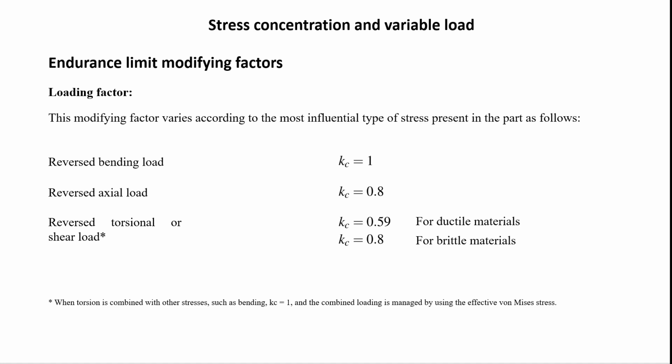Loading factor. Loading factor is another factor that is used because when we calculate the endurance factors in stresses, in tests, the gold standard used for the test rig or device you're using for testing fatigue failure in certain mechanisms is going to be reverse bending. But your application might not be a case of reverse bending. Reverse bending was the case that we saw with the aluminum part, the first video I played for you, where it broke due to a crack in the middle. So that's reverse bending, and that's the gold standard. Let's put it that way.